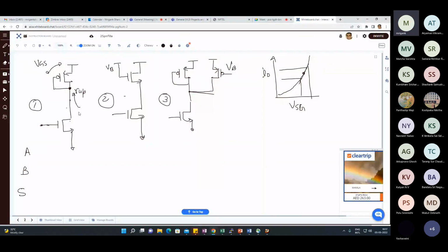Generally, by solving this kind of amplifier, we look at both R up and R down, right? Because ultimately, this is going to be a parallel combination, because in the small signal AC analysis this also becomes AC ground, this also becomes AC ground. We are applying the signal at the gate of this transistor, and it has its own ro, and then we need to figure out what is the load connected. R down is simply the ro of this transistor, the channel length modulation resistance, and R up is the impedance offered by this diode connected device.